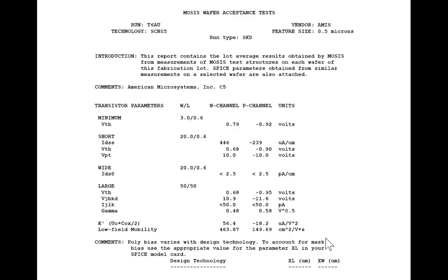Furthermore, they don't want other people who put a process together to know necessarily how to target the characteristics. We're working on a design right now that's due in about 2 weeks. And there's an ion implant that actually comes in at an angle relative to the surface of the wafer. And the angle depends upon the orientation of the substrate. We made the mistake of asking the supplier of the process yesterday, we said, what angle do you implant at? Proprietary. So, you know, a lot of things like that they're real sensitive about.